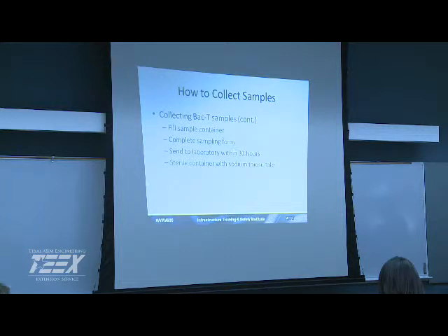That's what our lab would send out, and that's what we send out. Yeah. And a lot of times when we talk about this, we talk about best management practices. What's the optimum thing to do to ensure the best results? And that is, after you pull your sample, you need to put it on ice. Even if you're delivering it to your lab half an hour away, something like that.